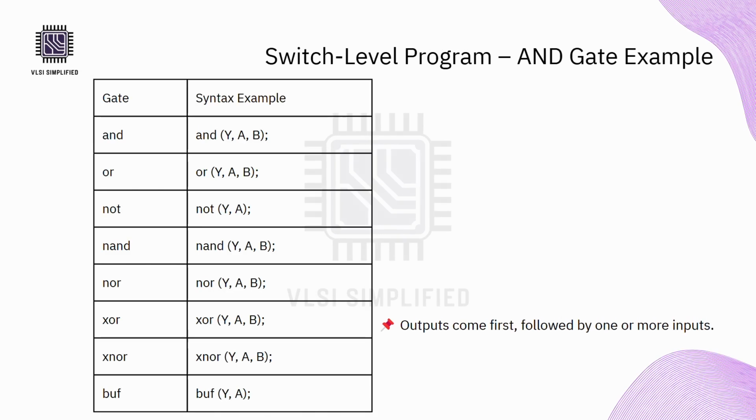Verilog doesn't stop at just the AND gate. It provides a variety of built-in logic primitives, and here's a quick reference for them. While you probably won't be writing full designs using just these gates, they are extremely useful for netlist level simulation, custom logic blocks, and post-synthesis debugging.